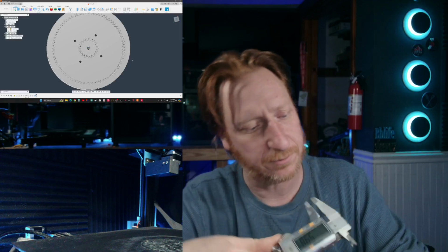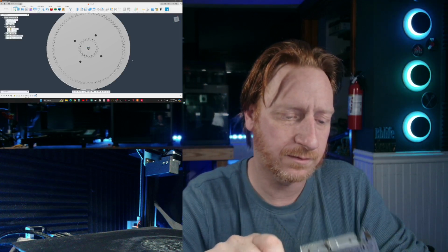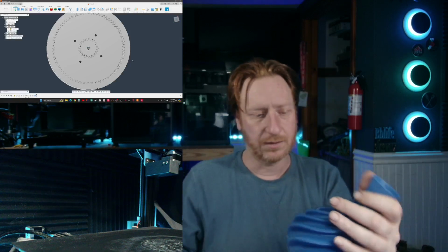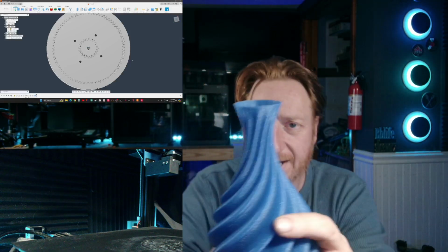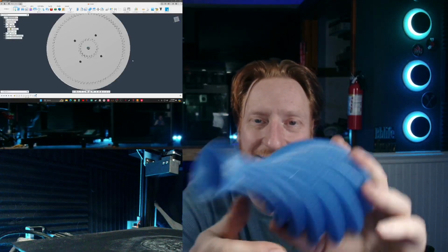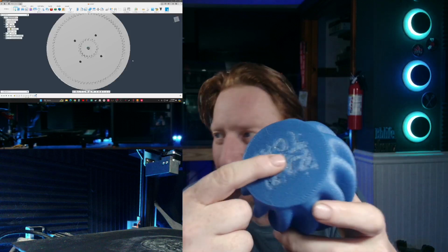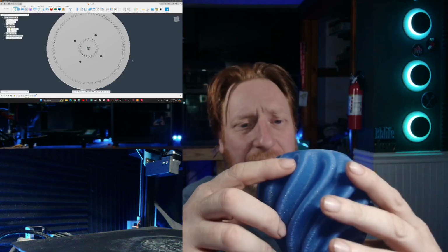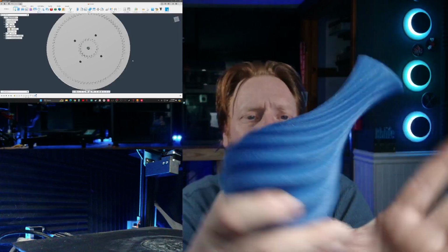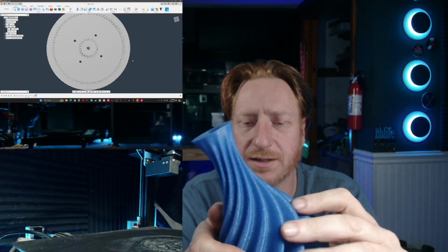Yeah, I don't know what it was reading. Because the wall thickness on here is 1.2. On the slicer it said 3. But that's a vase mode. That is solid. That's vase mode. I did have an issue down here with the bottom. It did not extrude properly on the bottom, but that's okay. I can just go over it. But yeah, definitely going to be using this.